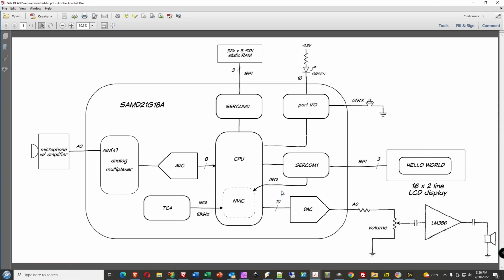In the third microcontroller lab, we programmed the internal DAC so that we could output a 0 to 1 volt signal that went into a 3 to 1 divider to create the signal that went into our power amp and played our speaker, and that allows us to play the output of the voice recorder on the speaker.